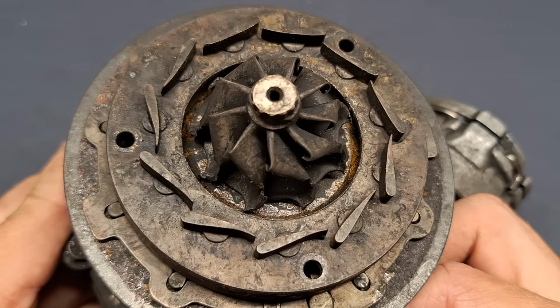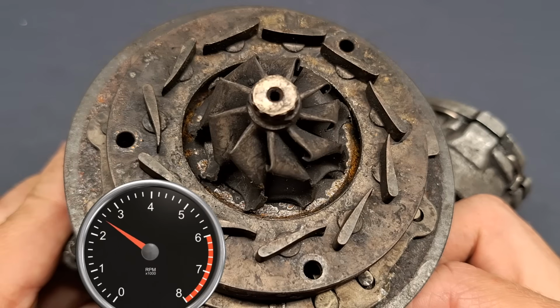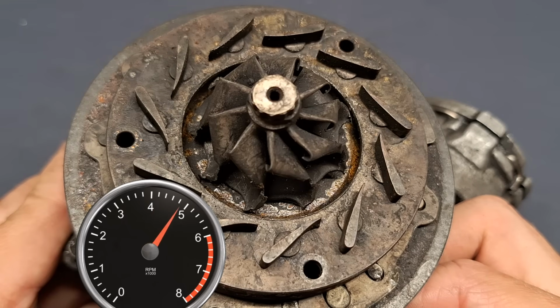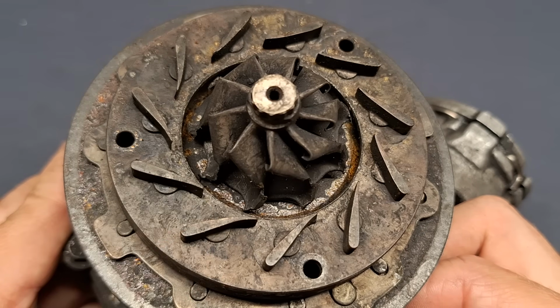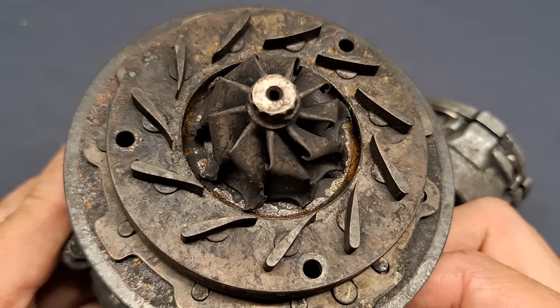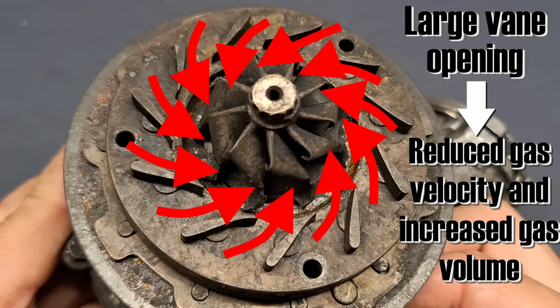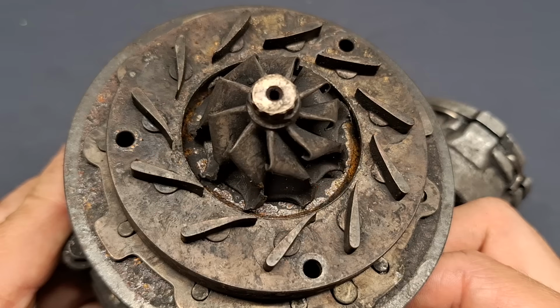As engine speed increases, the vanes open more and more to reduce restriction and allow a greater volume of gas to pass. When they're fully open, the cross-sectional area is actually too large, so essentially they act like an overly large AR housing, which reduces the speed of the exhaust gas to the extent that it prevents the turbine wheel from further increasing its speed, allowing it to maintain desired boost pressure.